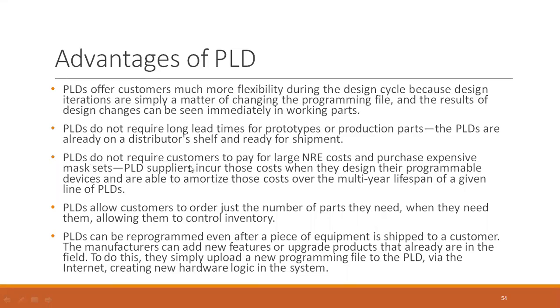And the PLDs do not require the customer to pay large non-recurring engineering costs and purchase expensive mask test sets. PLD suppliers incur those costs when they design their programmable devices and are able to amortize those costs over the multi-year lifespan of a given line of PLDs. They don't incur more cost on the customers. And PLDs allow customers to order just the number of parts they need, when they need them, allowing them to control the inventory.